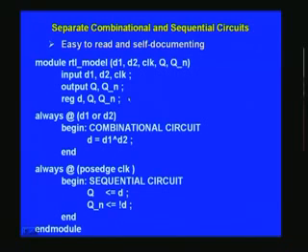And this is nothing but a D flip-flop which we have already seen. The only thing is we point out here the need to separate out combinational as well as sequential circuits. So that's what we are doing here. Here you list all the inputs, which happen to be D1, D2 and clock, and you can put them like this or separate them out in different statements. So is the case with outputs, and you just list them. We'll see more details when we actually put all the codes that we have learnt earlier in one file as a preparation for simulation later on.